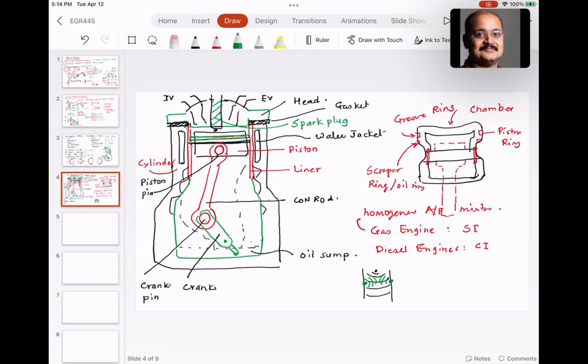So what they have is something called the octane level. So 87, 91, 93, that basically tells you about the amount of additive in the fuel that has anti-knock properties. So what usually happens is, when the car starts knocking, you retard the spark. You let some more time for the combustion to take place.